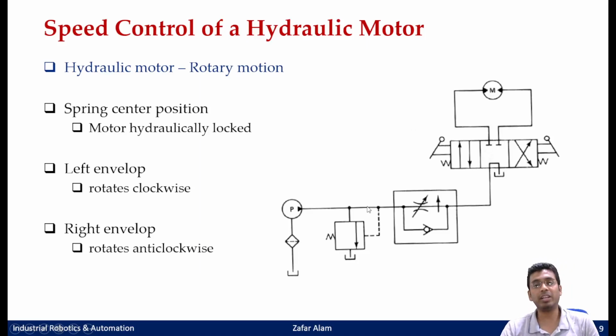Generally this valve is a flow control valve that actually constricts the flow of the fluid through this orifice. And the other portion has a one-way flow valve, so that this is a block position and this is a free flow position. This type of valve is common to both your hydraulic as well as your pneumatic rotary actuators as well as your linear actuators. For the linear actuators, you actually require this circuit. In case of hydraulic motors, you can only do it with your orifice itself.